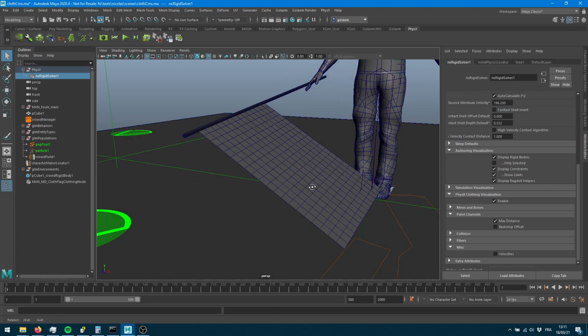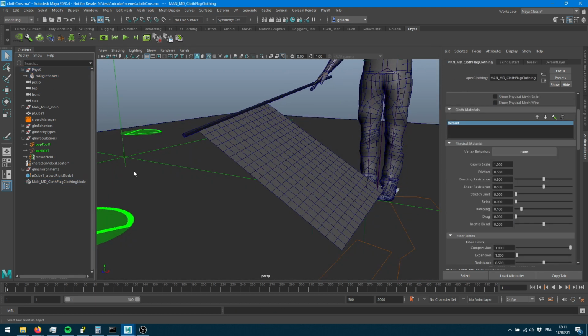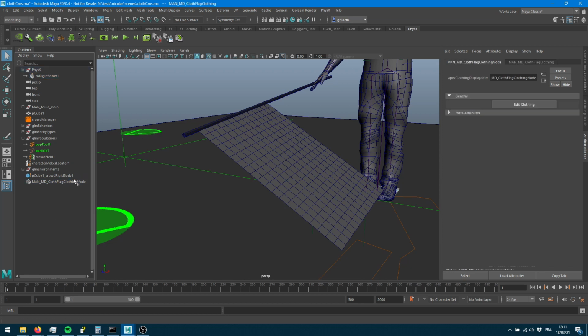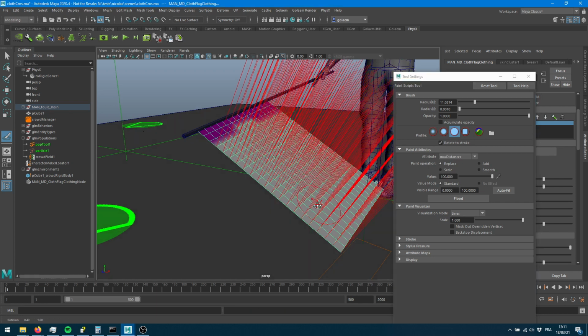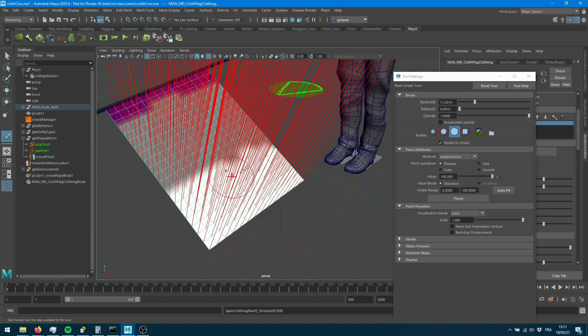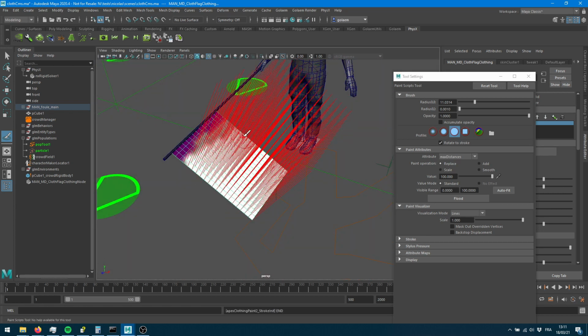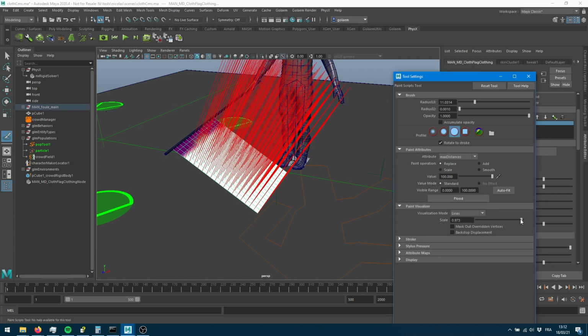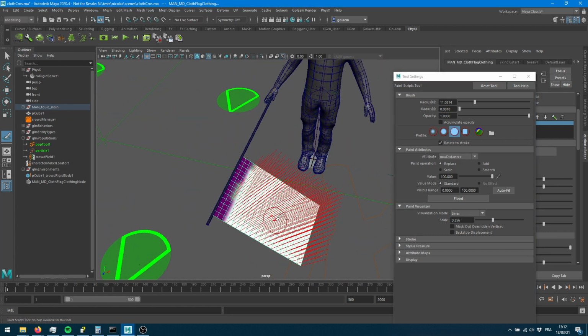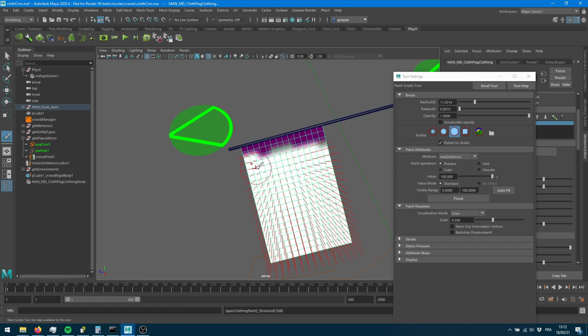So let's go back to the first position, back into our cloth node, and remove the max distance. Great. Let's go into the paint, and what I really want to paint is a 100 unit value. You can see that now I have full white, because I'm painting the maximum value of my range. It has the same controls as the Maya paint tool: you've got smoothing, flooding, you can scale your data, you can delete and paint other values. So you've got the usual controls. If those lines are too big for you, you can scale them down so they don't go through the full display. And I'm going to roughly paint my flag here.